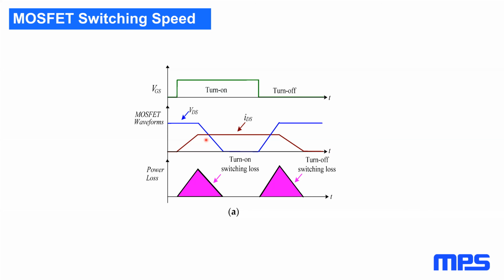Calculation, I don't know that anybody bothers to calculate. To be honest, most people put 10K ohms there. Again, it's only there to keep the gate tied down in the case where the gate driver IC isn't driving the gate. And sometimes that relates to power supply sequencing. For example, if the main supply turns on before the gate driver supply, you do want something there to help keep the gate of the MOSFET from floating around. But I don't know of any calculation offhand. Obviously, you don't want to burn a bunch of power in it, but usually it's around 10K.